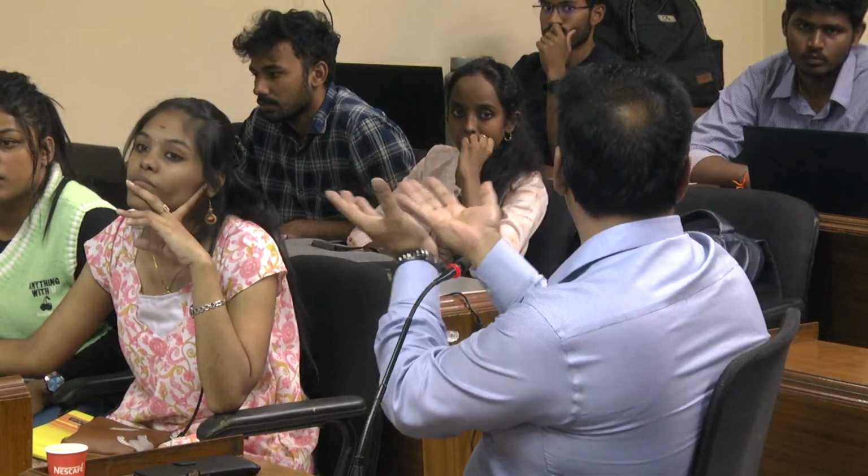So the next step is to name the inlet and the outlets. So for that we will have to select the face over here. So this naming is important because in the future we will have to add the boundary conditions. If you don't give the name, not a problem, it will work. But when you go to Fluent and give an inlet condition, you can't get the inlet. It will be like one body, one surface. So that's why it's better to give the name.